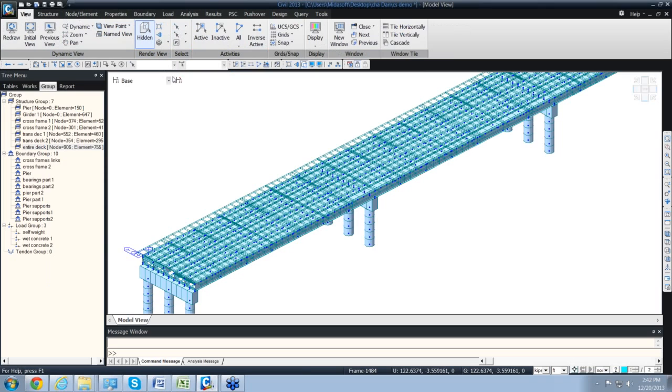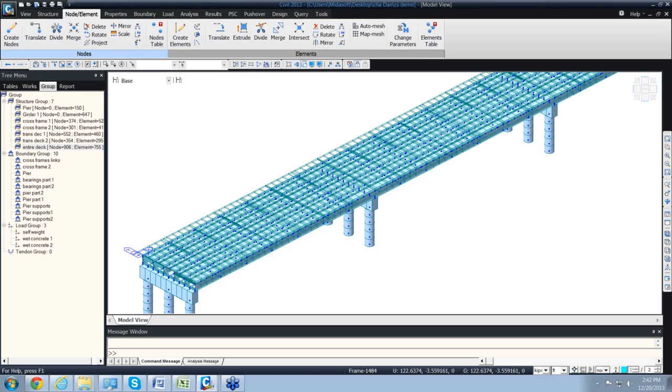All right. And let me talk about steel code check later. Question number 3D, in case of bottom laterals connections, call out rigid elastic link. Yes, I have used rigid elastic links. Questions regarding model development, measuring tool rotation, moving portions of structures around an axis. For that, I have already demonstrated to you the translate tool and the rotate tool. So we have all these tools that you can use.